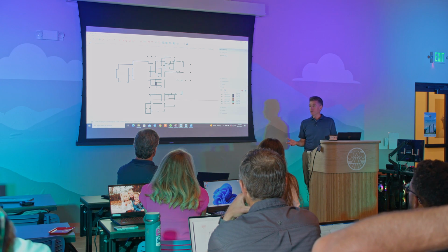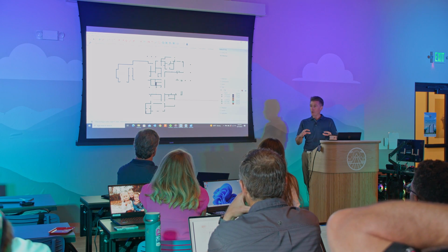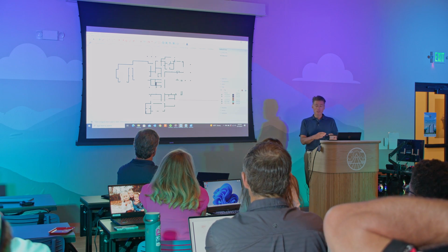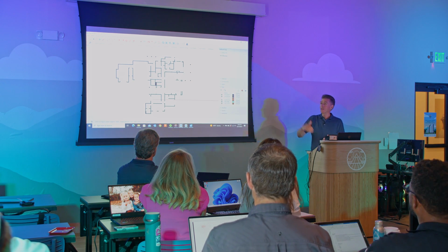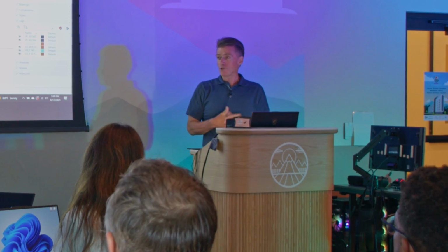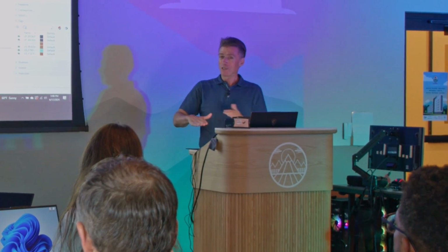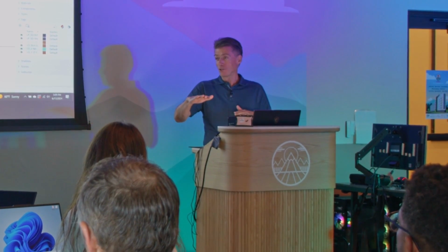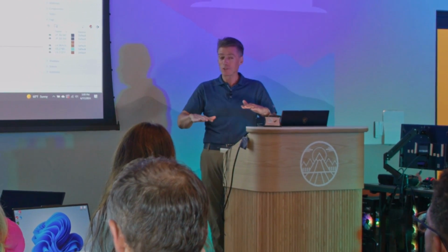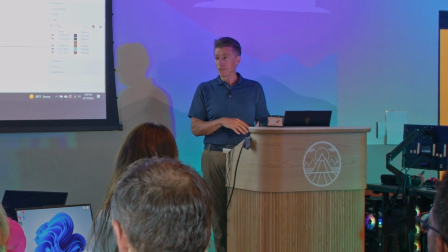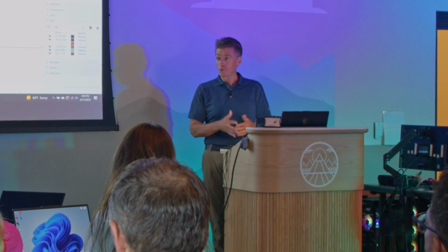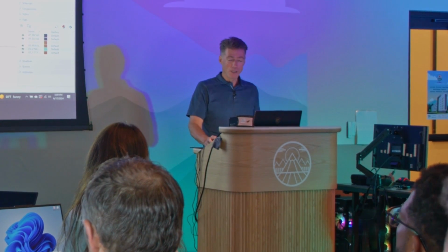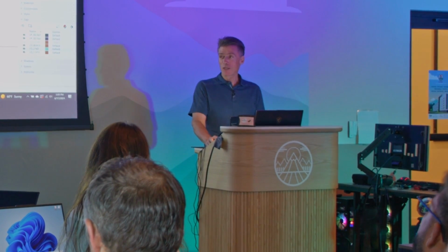Some I can't, and I just give up, and then in layout, I'll actually just put a white rectangle, a scaled drawing that I measure and place on top if it's a clear story that's 9 feet off the floor. Because there's no other way to do it if it's a section cut. I mean, I shouldn't say there's no way. You could do it with multiple section cuts, because I do this with garages that have big offsets. And then you have to weave it together in layout, which works really well. You don't see where the weave is at all. But there'll be multiple seams that you have to coordinate.